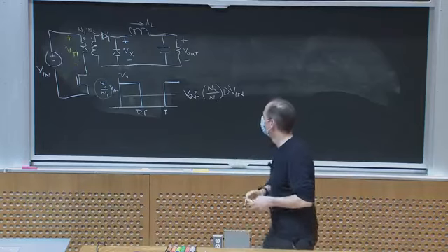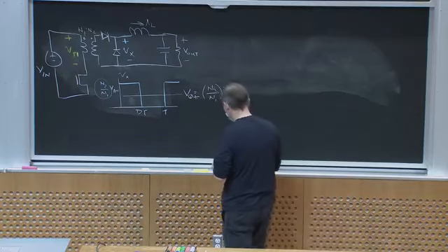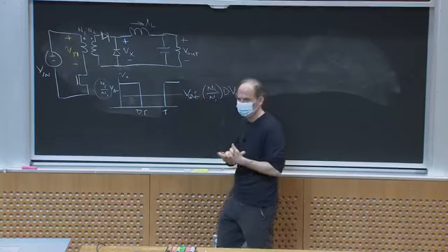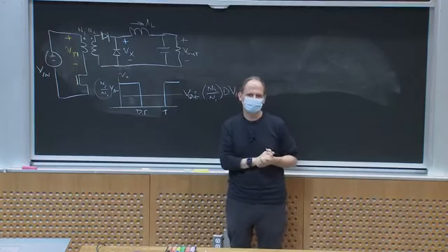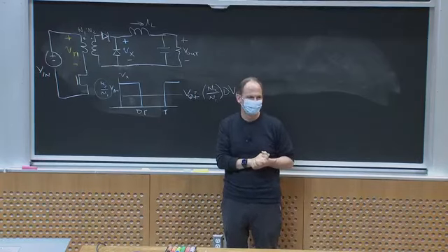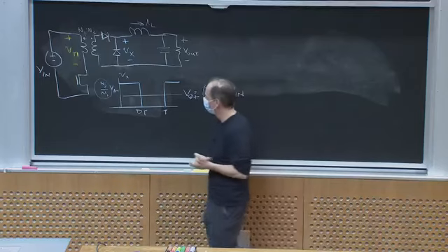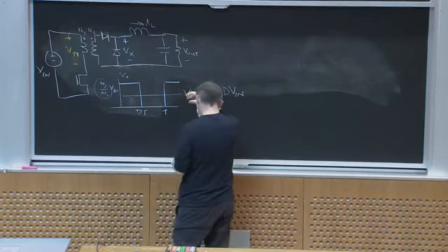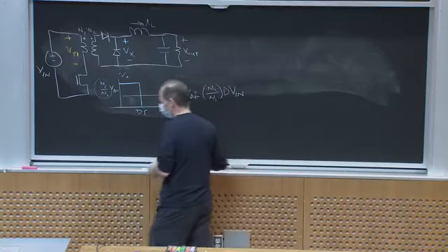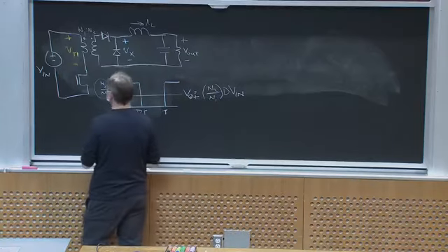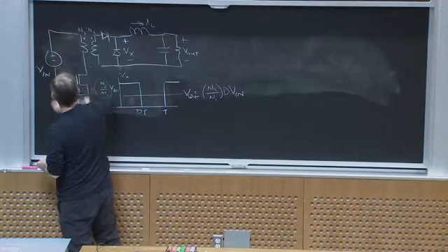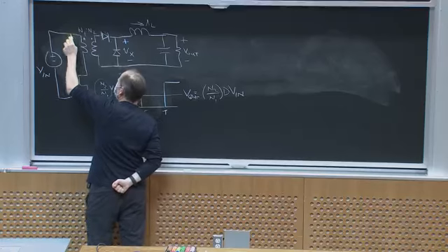That's great, but notice that I again have a transformer here. And so I better think a little bit carefully about what the magnetizing inductance does, right? So let me come back here and say, okay, let me put in my magnetizing inductor. So here is L mu 1.